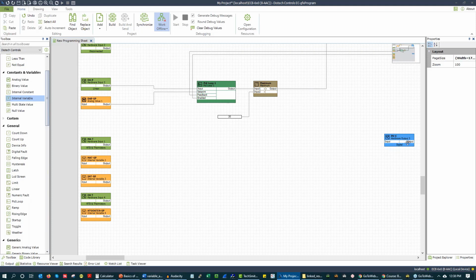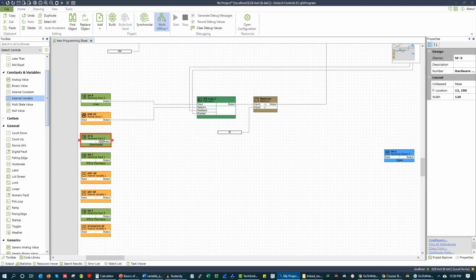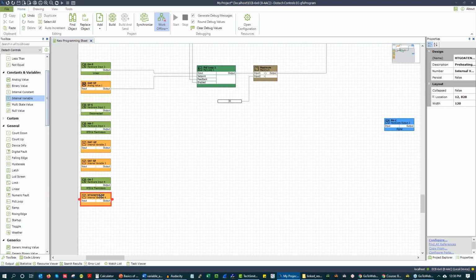We've got our minimum runtime, which we're not going to do yet. We have economizer is present, which we'll talk about in just a second because we haven't written any economizer code yet. And we have the supply fan status, which we know is up here. And I'm just going to drag it down here to make it simpler. And then we have this convoluted mixed air temp drops below. So we're just going to call this freeze protection set point. So we'll just copy this. And I don't want to copy that one. I'll copy this one, just because this one's not got a description on it. We're going to call this mixed air temp low limit SP.